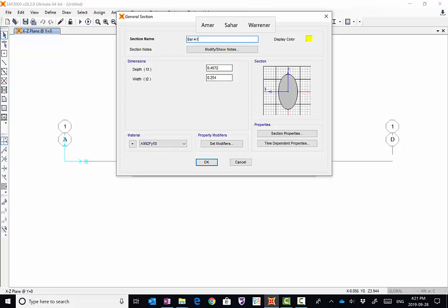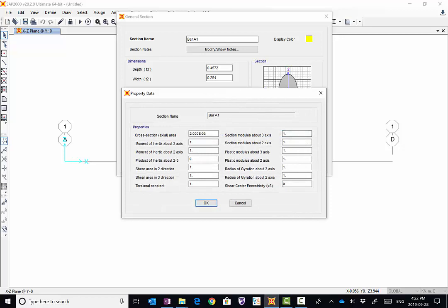Now for this section, the material we defined before. That's why the first step is to define the material. I have to link it to the material that we defined, which is called steel. So now we have E times A. The black box will understand right away that it will take the E value from the steel multiplied by this cross-sectional area. To make sure that everything is correct, go to section properties. We have the area defined here.